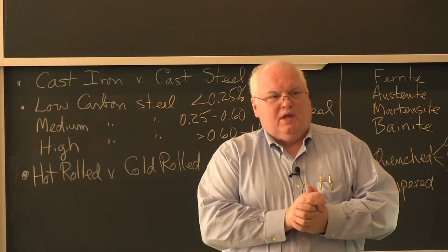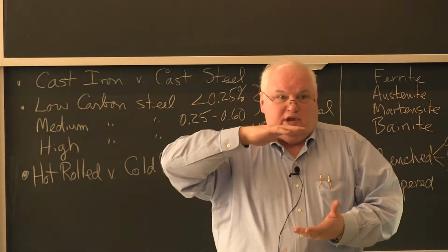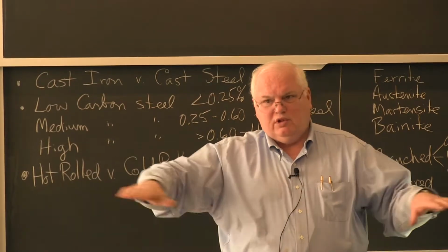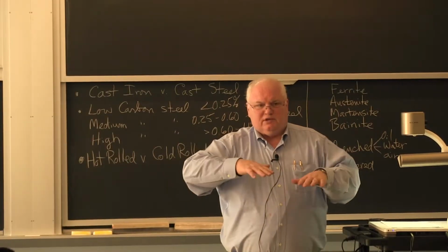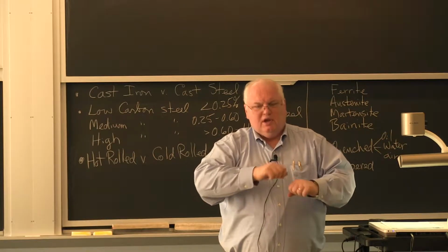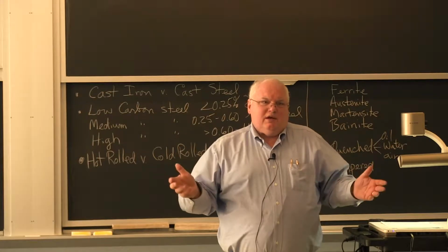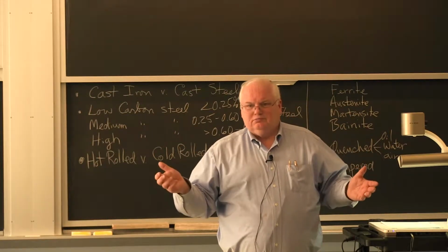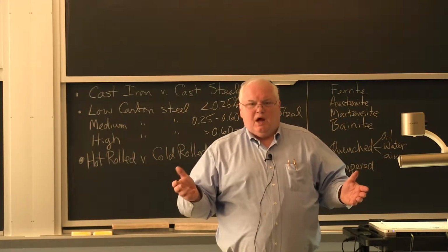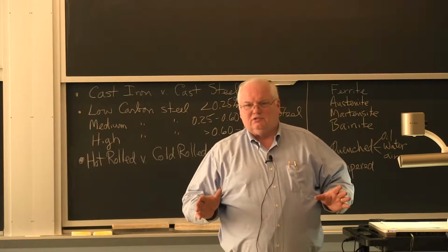Let me back up. Steel is made by casting, in the old days, like 20-inch thick ingots and rolling them out. It's basically what they call breakdown rolling, and you forge it down to about 4 or 5 inches thick, and then you go through a hot mill. And a hot mill today might cost you $1 billion, in today's terms, okay? A whole steel mill today might cost you $15 billion.